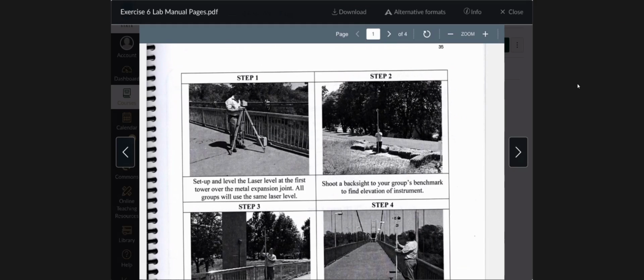It's a red, infrared, but it's not infrared. It's a visible red line, and then the laser will rotate once you turn it on. So when it spins, it creates a horizontal plane of light. So this laser takes the place of somebody looking through the instrument and taking a measurement on the rod. Okay, this thing will level itself once you get it to within a certain range. Turn it on, you can hear the gears inside leveling it, and once it's level, it will start rotating.